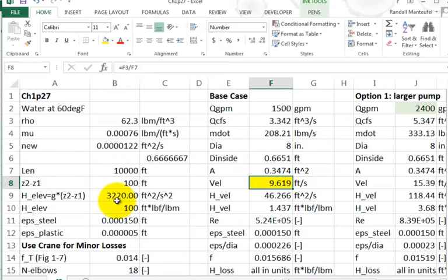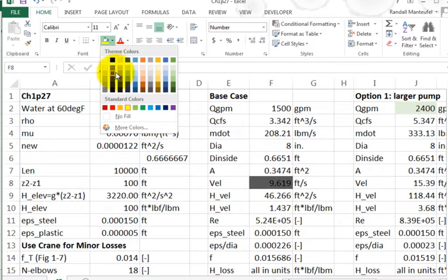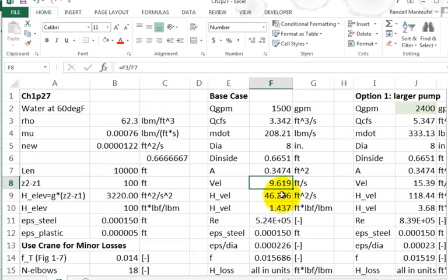It's moving pretty good, right? We don't want to boost it to 20 and 30 foot per second. It's not good for the pipe. So anyway, that's a pretty moving velocity. You're going to have a high velocity head with that velocity. Reynolds number is pretty good.